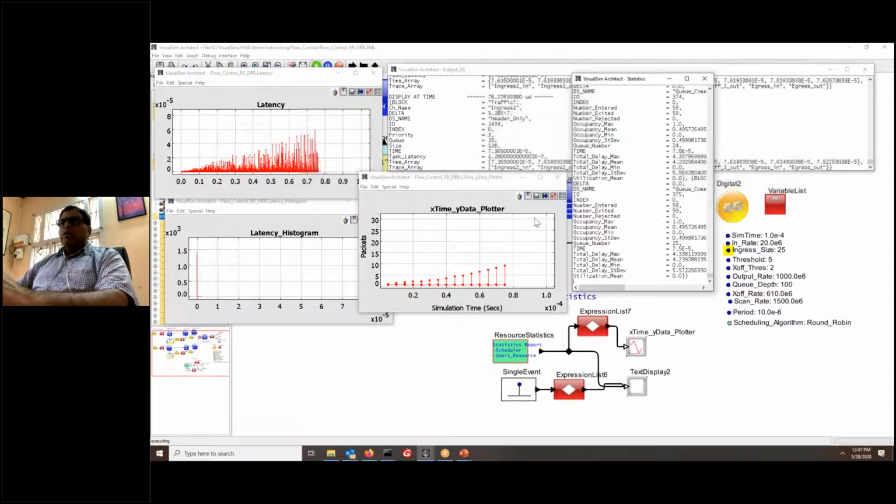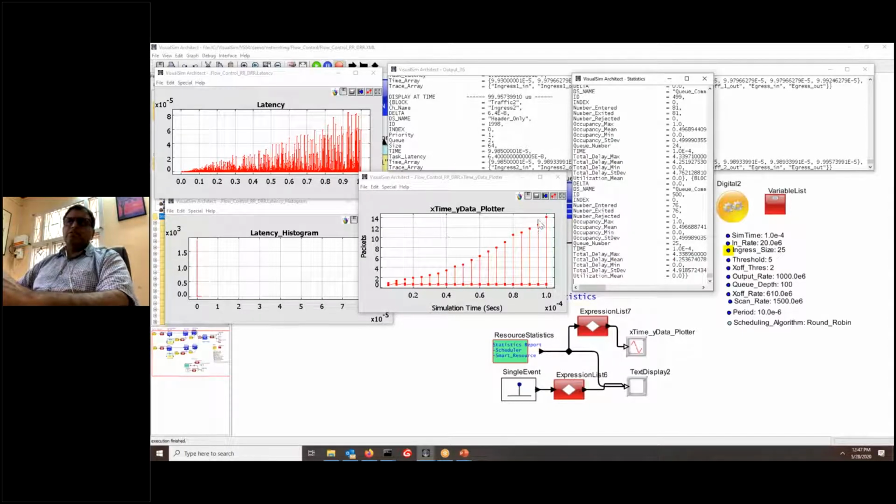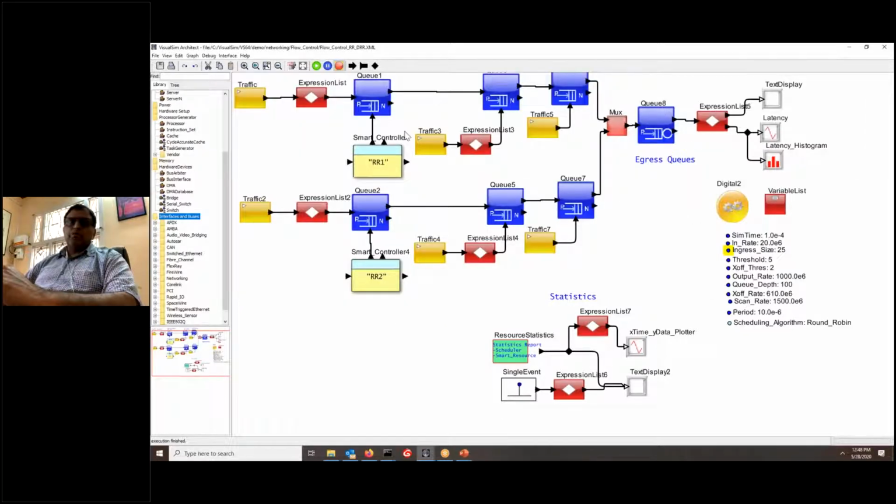So notice here, earlier we were buffering to about 30 when I had 15 channels, but when I went to 25 channels, my buffering dropped to 14 because it's the same amount of data samples that's been split across more number of channels. So that way I can reduce the amount of traffic going on to each channel, and that way reduce the amount of buffering. So what do I know from here? I know how many ingress queues I need. That's one of the specs I need. I know what's the buffer occupancy in each one of them. I know what the flow control is between all of them. So I get all of this information using this particular model.